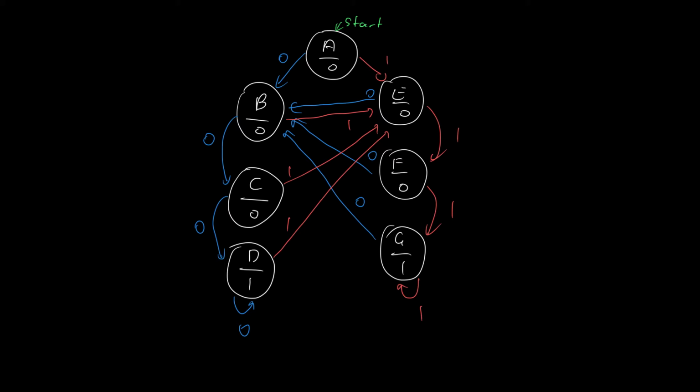We just change the localparam statement. There are 7 states, and so we're going to use 7 bits to store our state, and basically 1 bit is going to represent 1 state.